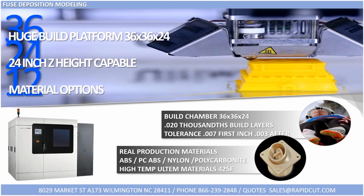So this process in general is going to build at a 20 thousandths build layer. Where PolyJet excels at the fine features, FDM is not going to be able to capture those same types of features. However, in larger parts, we found in real world applications that FDM is the tightest tolerance of the group in what we call final parts. When compared to SLS on 12-inch parts, they were holding a tighter overall finish tolerance. However, it does remain at 7 thousandths for your first inch and 3 thousandths thereafter.